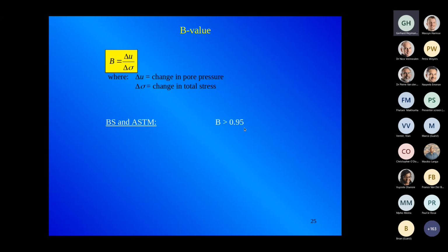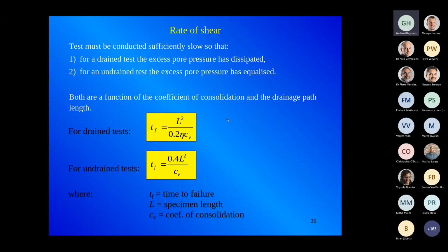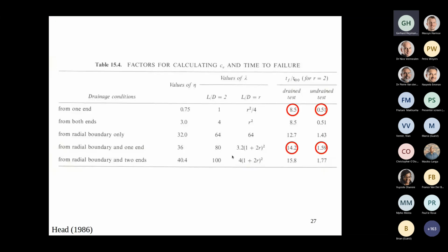Second thing to do is check the rate of shear. And those are different for drained and undrained conditions. And there are equations. If you want to read more about that, a book like Head is very nice. You can go look at that. Very few people actually use these equations. What they do is they use a table like this.